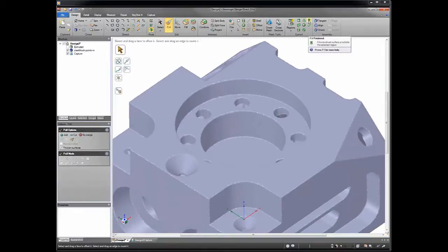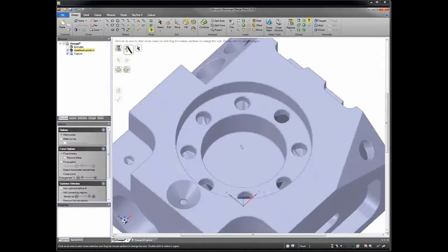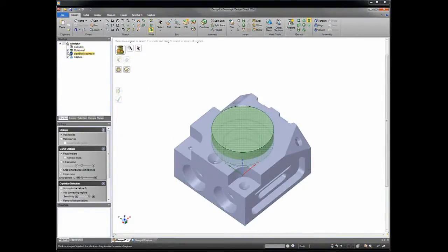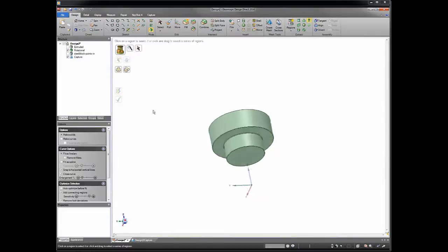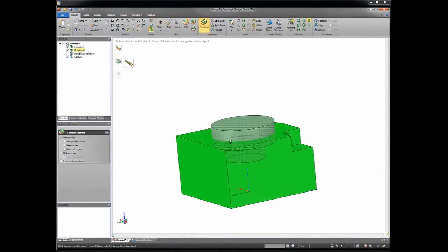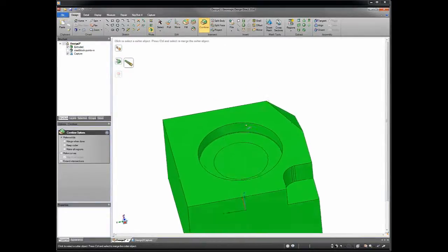We're going to do this as a rotational. I could do it as two concentric cylinders if I wanted. Here, though, we're going to pick these regions on the inside. We have some nice little tools to optimize that selection to make sure you're not picking up unwanted geometry. We're going to create this little plug almost. You can see this little body here. Then again, we'll use our combine tool to subtract that body from the inside. All right, so we have that little cylinder there.